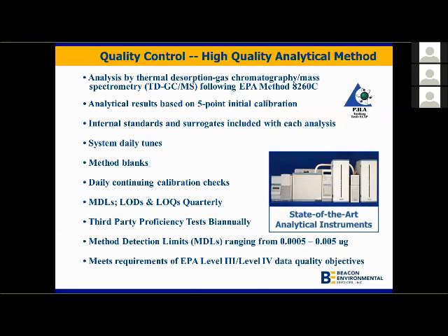Now, the data reported with a passive soil gas survey is in units of mass of individual compounds that are absorbed throughout the exposure period. Federal and state regulators are not accepting passive soil gas data converted to concentrations, but reporting the data in units of mass still meets the objectives of a passive soil gas survey, which is to collect high resolution data to effectively screen the site in order to focus where soil and groundwater samples should be collected, to identify whether a vapor intrusion risk might be present, tracking groundwater plumes, and focusing remediation efforts. That is to make sure that you are injecting or extracting those areas where your efforts would be most effective.